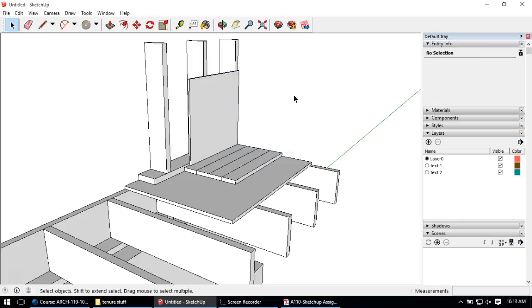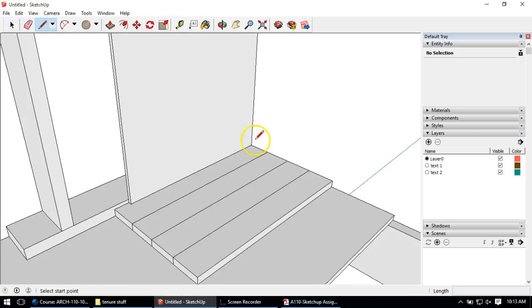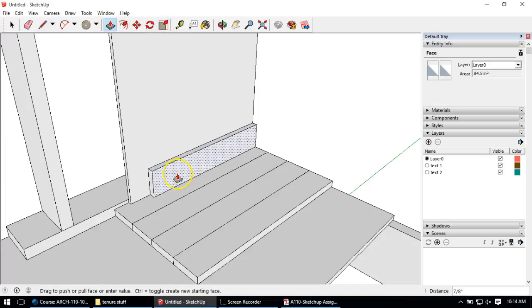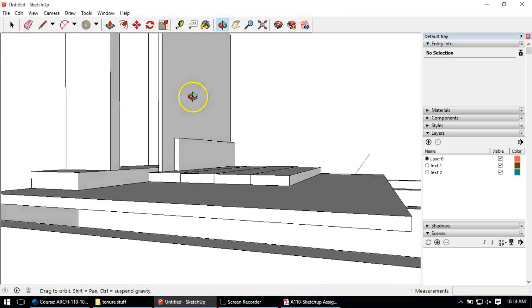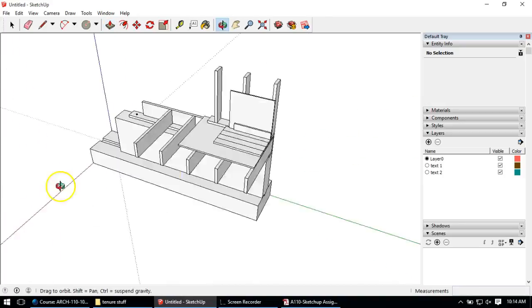And then note 8 looks like some sort of trim work, 4-inch wood trim. So I'm going to come out. I'm going to come up 4 inches, and it's going to visually come across shy of the surface a little bit. I'm going to come down and across. I'm going to pull this out. I'm going to say this trim is 3/4 inches wide, so I'll do 0.75 to show that trim there. And that's basically the first bit of drawing other than the notes is all right there.